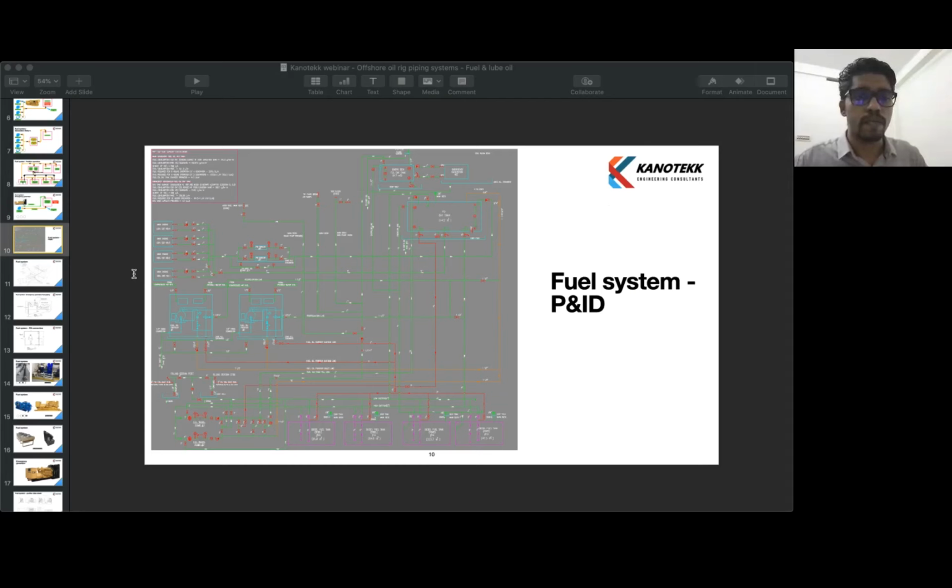Next question: do we use additional strainers for fuel oil lines to engines? Yes, we can provide additional strainers, like on the transfer pump discharge side. Similarly, the engines supplied with the generators will have separate strainers, like duplex filter strainers.